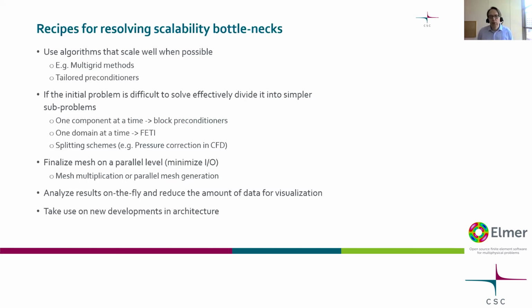Also for post-processing, it's often a good idea to analyze the results on the fly. We have a lot of features where you can analyze the results. No need to save everything and then open ParaView and try to analyze what the data is in one particular point. You can instead just save that one particular point to start with. Or if you want to study what the data is on a given line, why not just save the line? So these kinds of reduction techniques, like computing the integrals, etc., inside the code, make sense often.